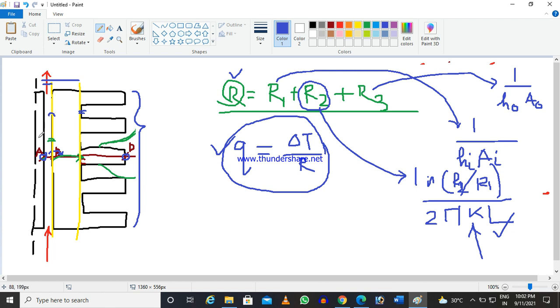So you can use SolidWorks, COMSOL, ANSYS, whatever it may be. Some other packages are there, I can't remember right now. So first you take the laminar flow as well as the heat transfer, and you couple these two analyses and find out the temperature distribution along this path.